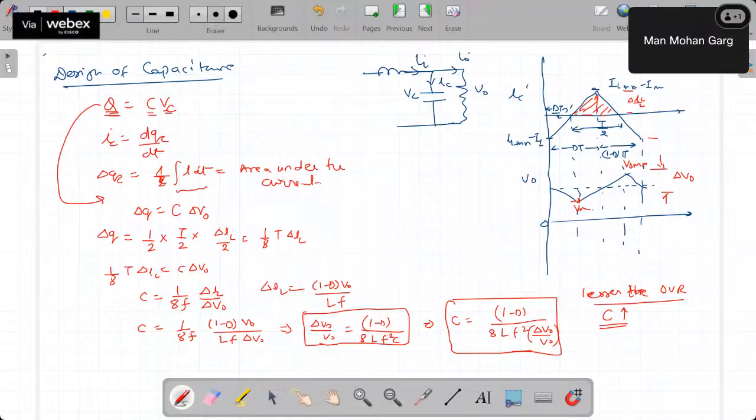What is the standard ripple during design? Yeah, it's 1% for standard power supplies. I will show some slides of my research also to you in the next session. What we discussed was just fundamentals. Now I'll go for the research part a little bit in the next one. So 1% is the ideal, 1% at certain times, 2% also. Sir, it depends upon applications also. But 1% is okay. Maybe for aerospace applications, we have to go a bit lower also. So in those cases, we have to choose the capacitor very wisely. And how this ESR makes an impact on these ripples, I will discuss in the next session once we discuss these basics of converters.